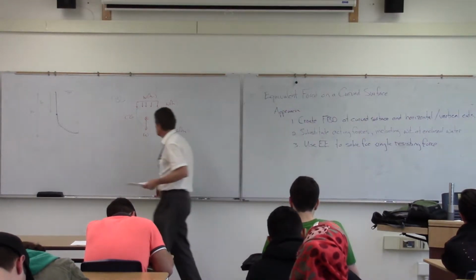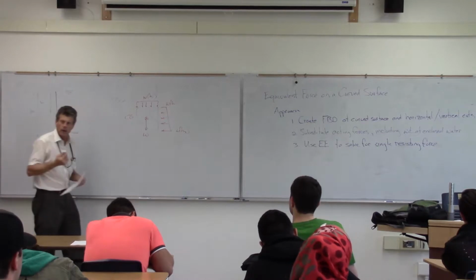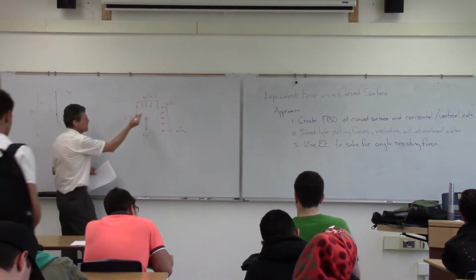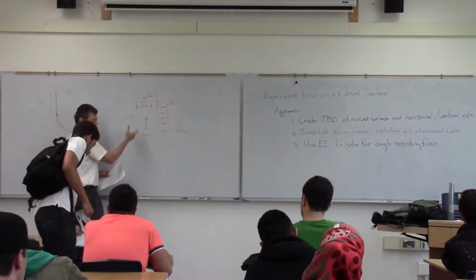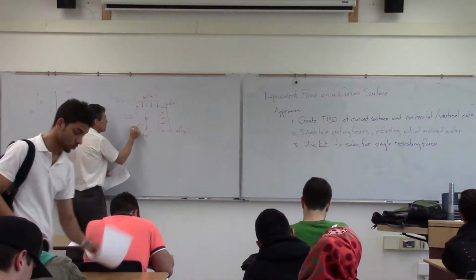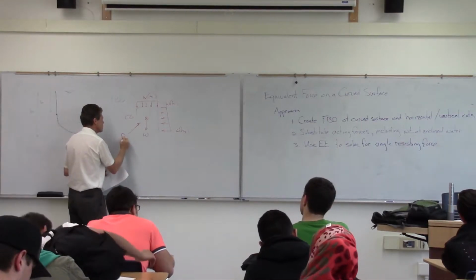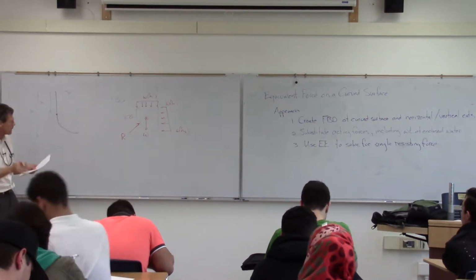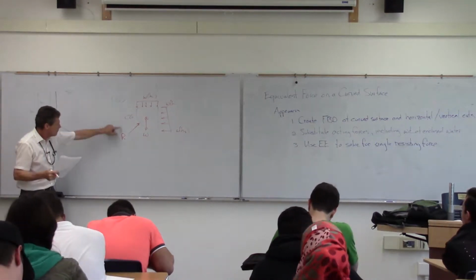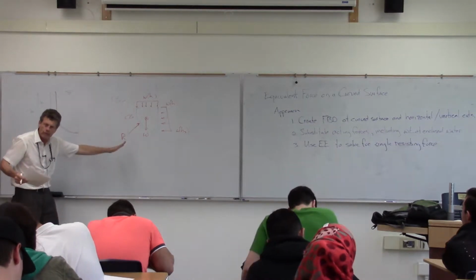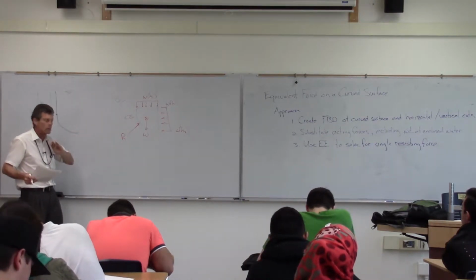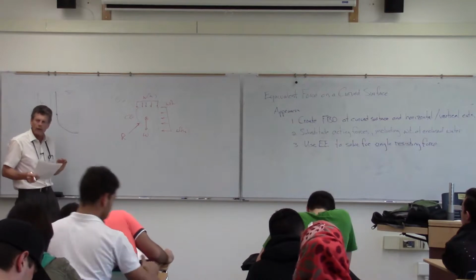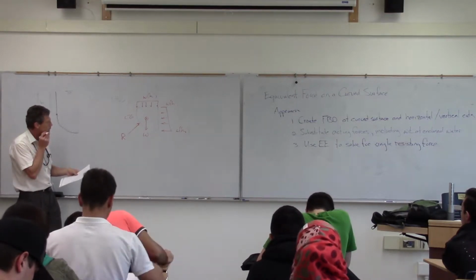What we're going to do then is say, okay, I've got all of this here. What I'm going to find then is, to keep this all, this is pushing down, this is pushing this way, this is pushing down. There's going to be some sort of a single resisting force that I can calculate. And this goes back to finding the force and couple and then moving that force to the single force location there where the couple goes to 0. What we'll have is then a single resisting force there.